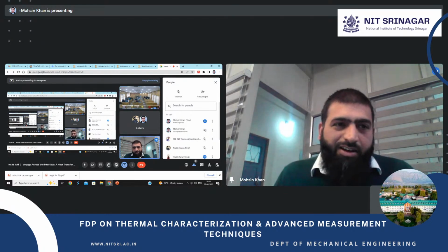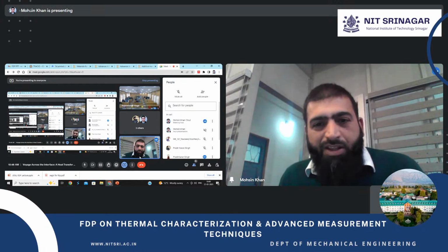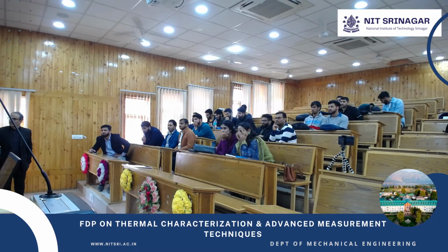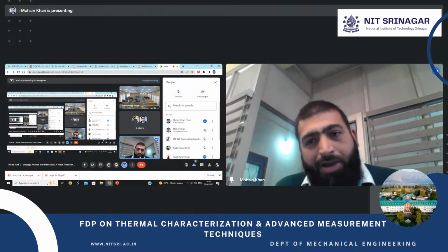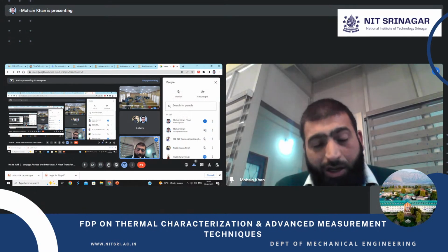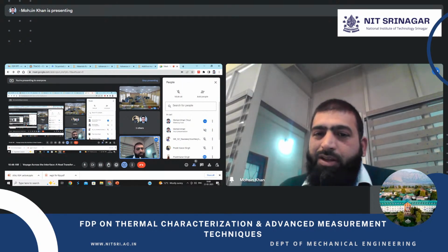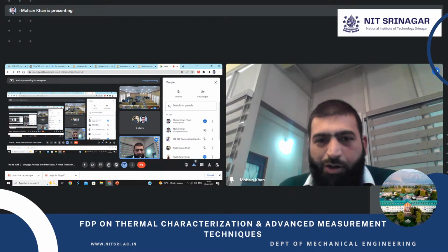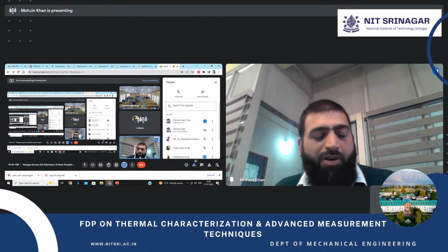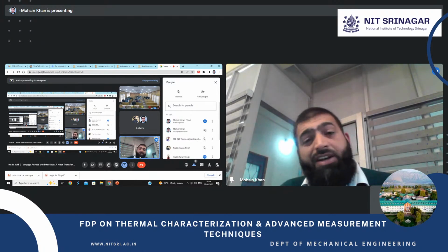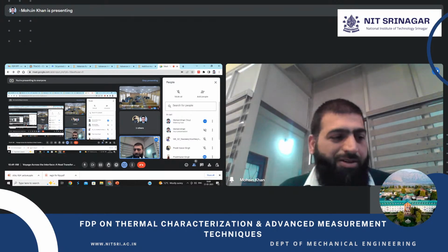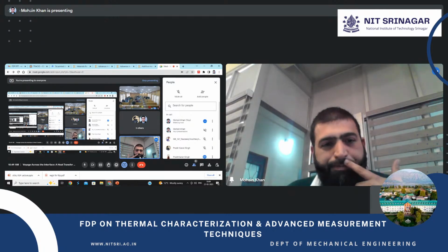This is an experimental procedure, and you have to see what the aim is and what the role of adding the surfactants is. If I am manipulating the fluid properties alone, then it has to be added prior to the addition of the nanoparticles. If the addition of the surfactant is more effective after adding the nanoparticles, then it varies from case to case. You actually have to see how it works for you. In certain cases, we treat nanoparticles separately before adding them to the fuel. So it all depends upon your requirements.